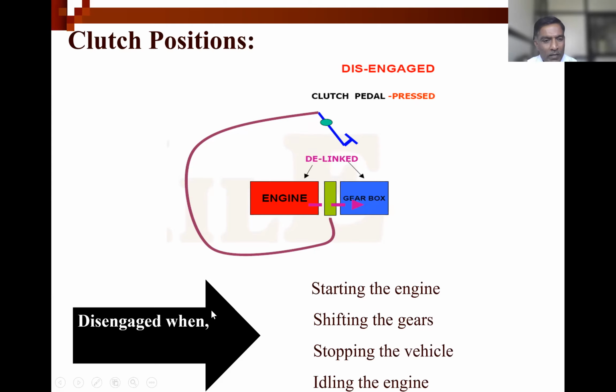So, disengaged when starting the engine. When we start the vehicle, if the vehicle is in neutral gear, we do not operate the clutch, and if the vehicle is in some gear, in that case we disengage the clutch to start the engine. So, disengaged when starting the engine.